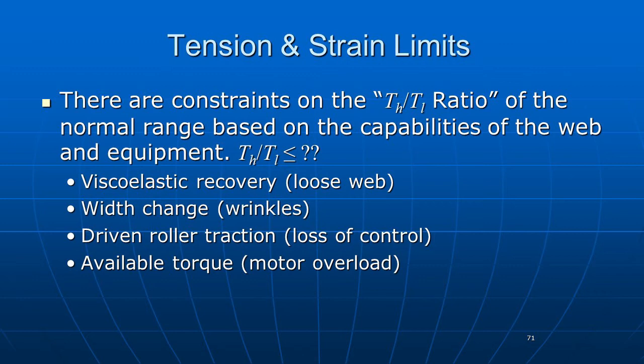If you stretch them and relax them, the instantaneous recovery will be about 6-to-1. So if I stretch it to, let's say, 1.2% strain, it'll relax back to 0.2% strain, about a 6-to-1 recovery. So you can't ask them to do any more than that. Width change: big tension drops over driven rollers can lead to wrinkles.